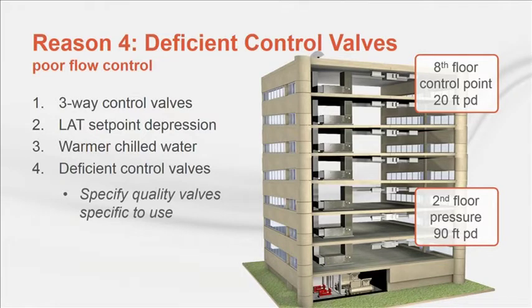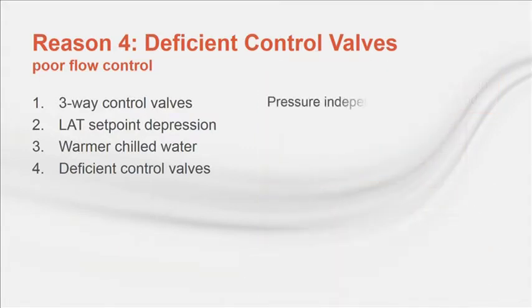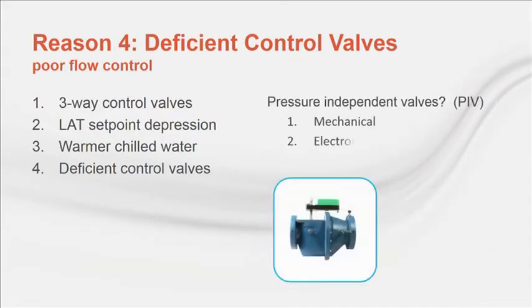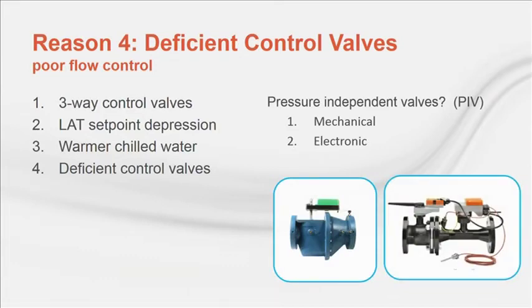Properly selecting control valves for their design flow and their location in the system is important for good control and delta T. Which brings us to the question of pressure-independent control valves. There are 2 technologies of PI valves, mechanical and electronic.